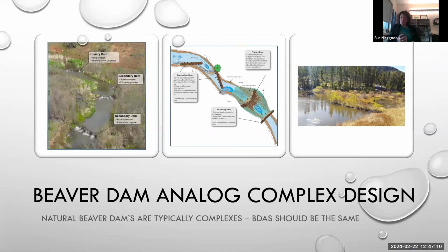So, how you design a beaver dam analog complex and how we've been looking at it as well. There are some good reference manuals out there. There is Joe Wheaton's out of Utah State. They developed the low-tech process-based restoration design manual, LTPBR. And there's a lot of good information in there about all different types of beaver dam analogs, along with other low-tech process-based restoration applications.